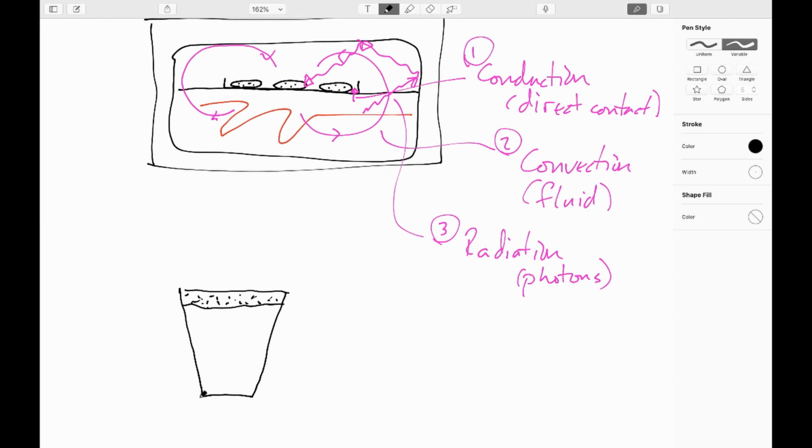What's happening is the glass is in contact with the bar, so you wind up getting a heat transfer in at the bottom. This winds up setting up a convection cell because, after all, the beer is a fluid. But it turns out that this convection cell goes up through the middle and down the side, so the opposite of our oven.